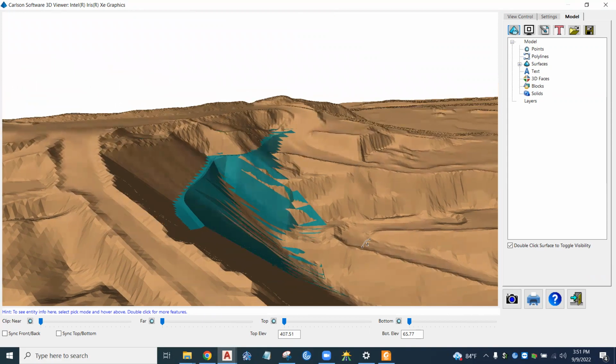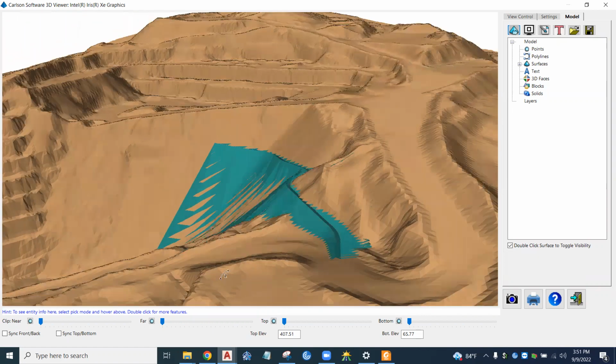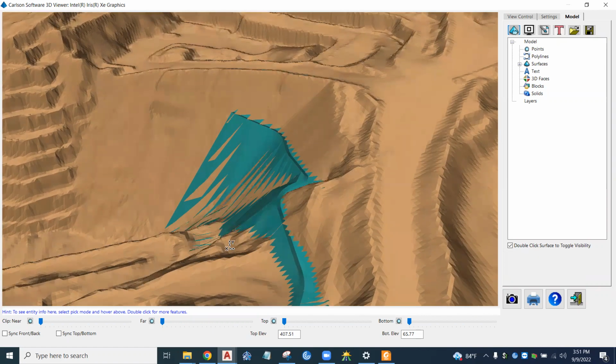Problem is, on the fill side, I go out to that edge and I go down at that slope, and the only way I'm going to actually hit that slope is if I go down steeper than that slope is, so that the slope will eventually run into it, going off at a flatter slope.